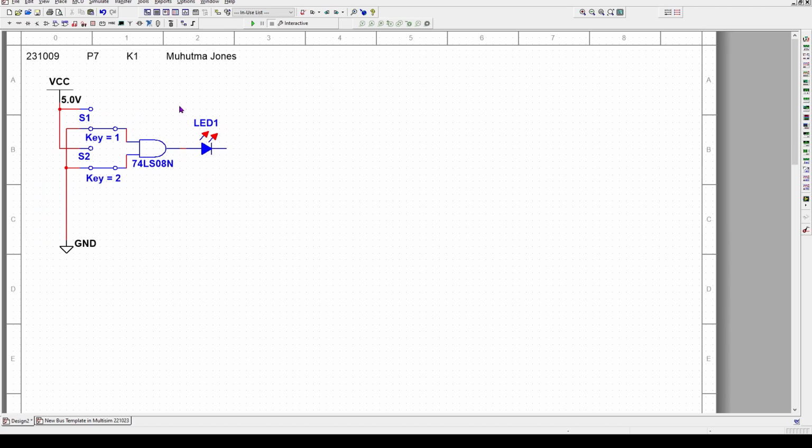But the distance between two dots on the screen is a click. And so I say always make one click show, because if you got two components touching and you're assuming that they're hooked up and they're not, then you got to dig around to find out what's wrong with this circuit. It's less troubleshooting if you just make sure there's a click of net or wire between them.